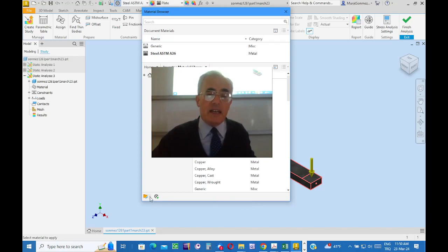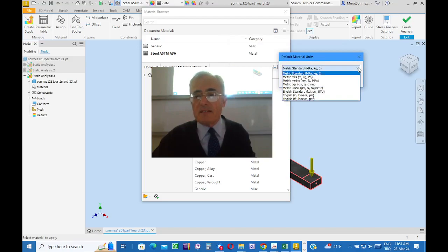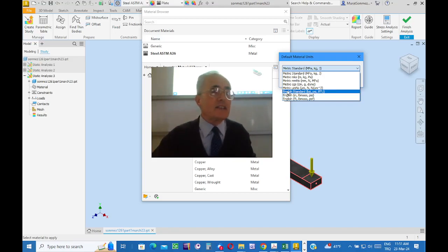To be able to see the results of the calculation in the SI unit system, the thing to do is bring the cursor to the lower left-hand corner. There's an arrow here. Click, drop the list, and select Set Display Unit Options. In the dialog box, the automatically selected option is English. If you want to see the values in, for instance, KSI, not megapascal but kilopound per square inch, thermal values in British thermal units, etc., then select English.